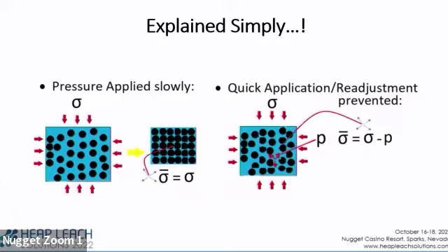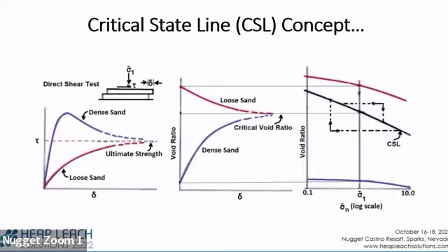In most circumstances, we see some sort of cyclic mobility, partial loss of shear strength, but it's in the spectrum of liquefaction. It's the same mechanics, just not fully fluidized. Now, one interesting part of this phenomenon is if you have a loose sand, so the grains are kind of separated, and you load it, either just normal load or shear load from an earthquake, the particles will come closer together, or they'll compact on each other, so it gets smaller, it contracts, and that's what creates the water pressure.